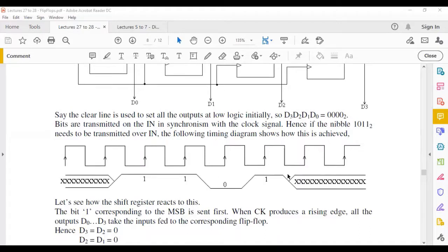Whatever is sent on a line would be high for some amount of time. If you wanted to send a 1, it's going to be maintained high, and then this is going to be transmitted along an optic cable or a normal cable. And then if you wanted to transmit another 1 after this one, meaning a high, you would maintain the line, but make sure that this corresponds to your rising edge. If you wanted to transmit a 0 now, because the next bit you want to transmit is a 0, you're going to change the state and make sure that at the next rising edge, this is transmitted.